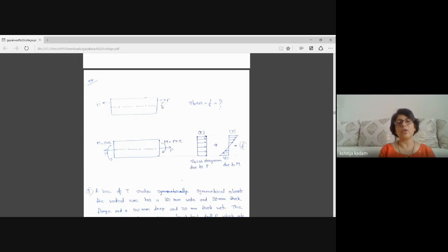I am having this large value of E. So you can visualize that the rod will deflect, with an increase in length as well as hogging, because the force is not applied at the neutral axis, it is applied at some distance. So what will happen? I can translate my given problem into the problem shown in the next sketch below. It will observe an axial pull P, and it will also observe a moment which will be equal to P multiplied by eccentricity E.